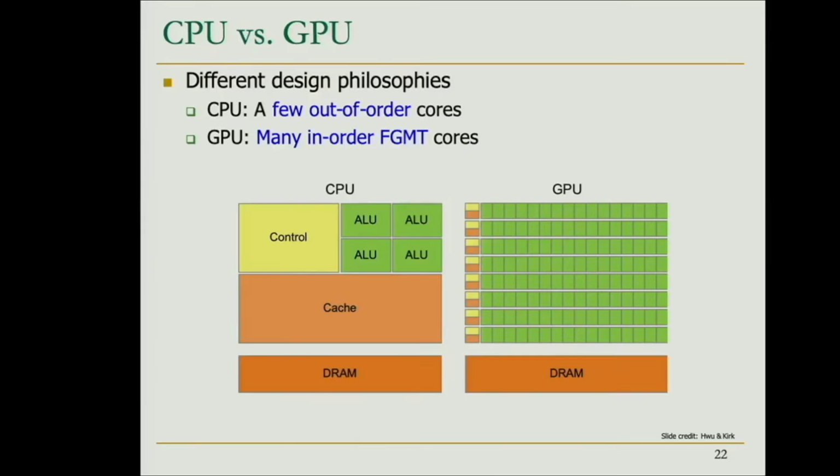What we need for control and for caches is much smaller, and this corresponds to something old like this GTX 285, where we didn't even have L2, or we couldn't use it for the general purpose pipeline. Now we actually have an L2, but the size of these caches compared to typical sizes on CPUs is significantly smaller.